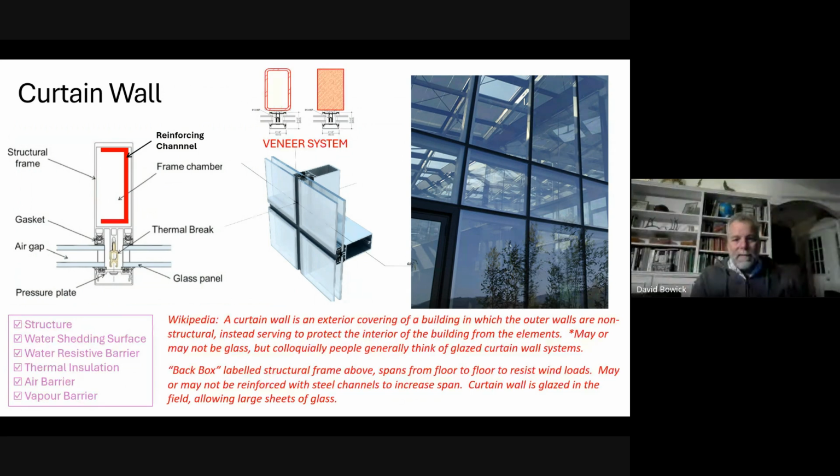The reason we need it to take a screw is because in the field, the curtain wall extrusion is installed, the glazing is applied, and then a cap or a pressure plate comes on and gets screwed to retain the glass. And then it's capped, visually capped.